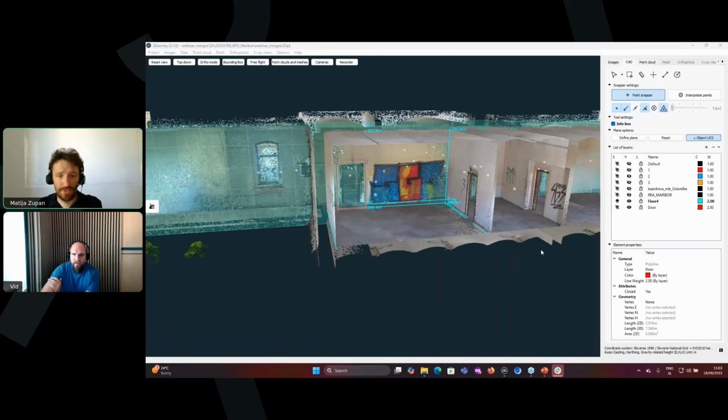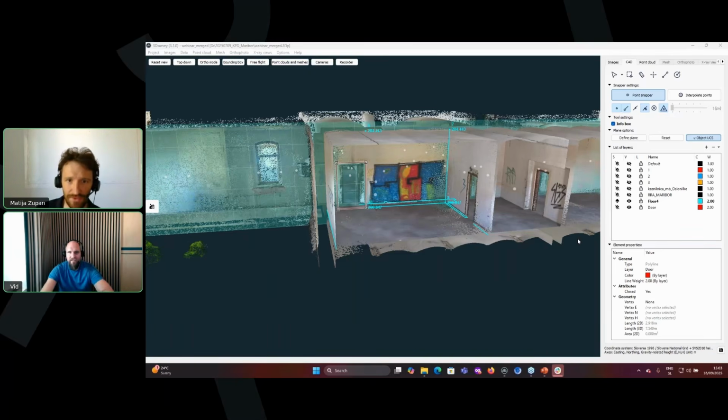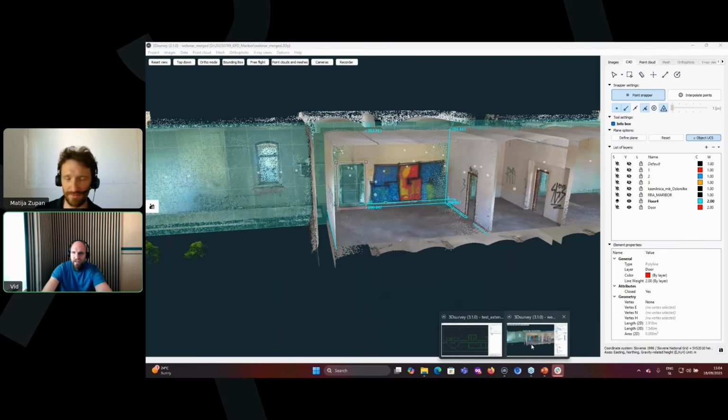Okay, so the next question sort of ties on that. If not georeferenced, can you adjust all data sets, photogrammetry and SLAM, terrestrial lidar, and GCP in 3D Survey through user-defined alignment and least squares on the final solution? Yes, you do that. So you would do that with the manual registration. Would you care to? Yeah.